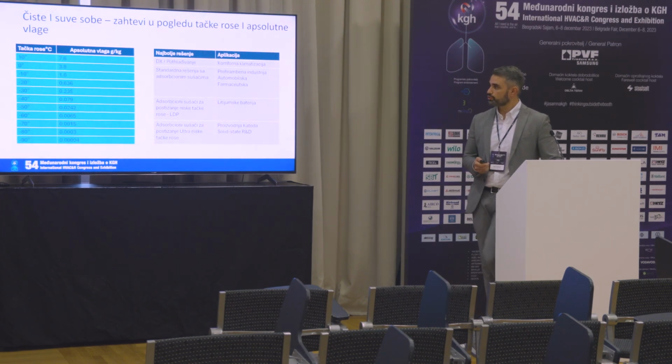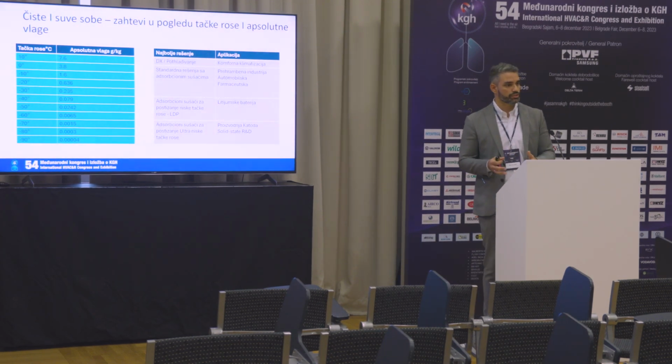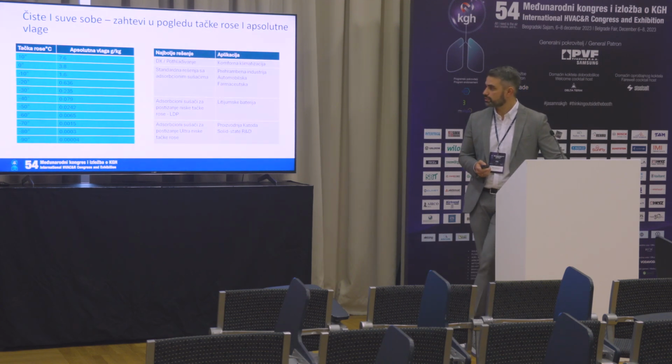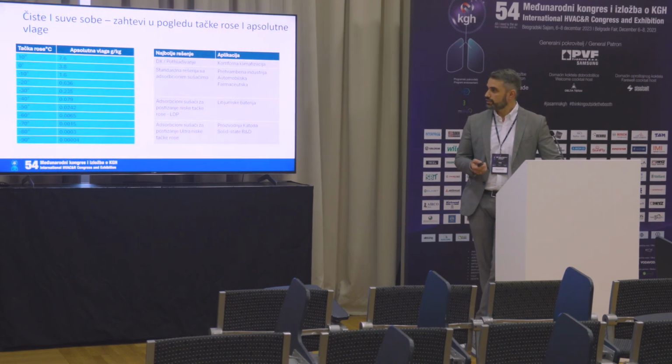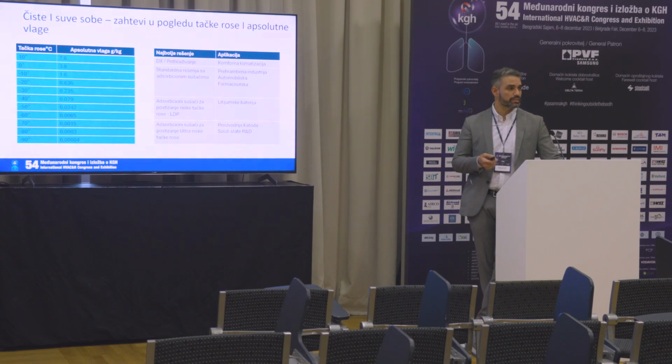In terms of low dew point, we have comfort climatization, which is usually done by cooling and then reheating in order to reach 40 to 50% relative humidity at a standard temperature of 20 degrees. And this is a low dew point of around 0.